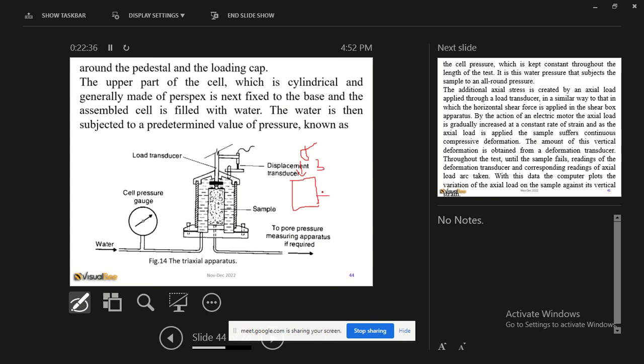sigma 3 initially. Now this sigma 3 must be related to the consolidation test. If you remember, I have to draw it out to make sure you understand. In the consolidation test, this is the e, and this is the stress. There is a nice curve here. I taught you this. Then you draw a curve there, and there's a pre-consolidation stress.